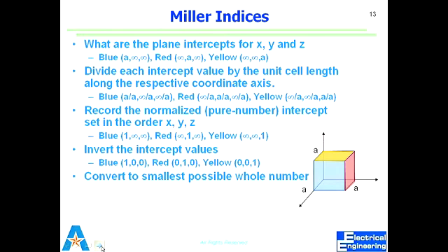If I have a plane where I say it's 0, 1, 0, what would that mean? It's the red plane, which is parallel to x and z, in the direction of y. Now I know this, I will look up what the material is and what the unit cell looks like for that material. That will tell me how many atoms should be in the red plane, blue plane, or yellow plane.